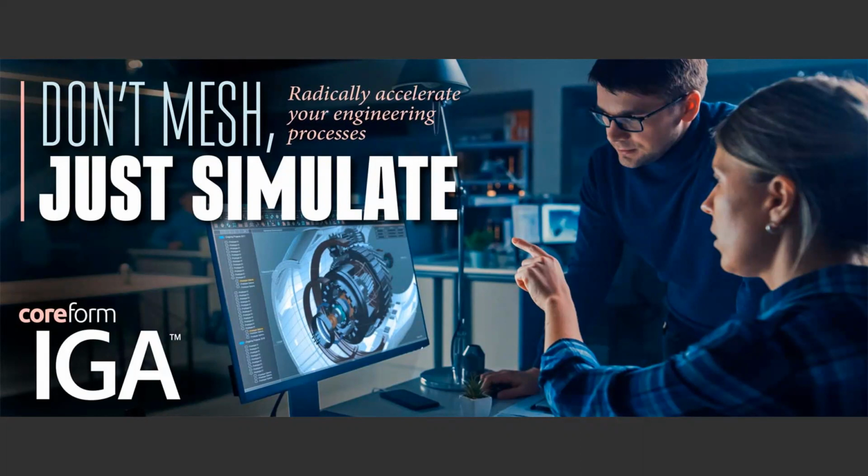In our case, the condition number decreases, or if it increases, it only increases by little bits as opposed to doubling. Those things now allow you to efficiently use iterative solvers as opposed to direct solvers on the linear equations. So all these things are being pieced together, where we're seeing that we can be much more computationally efficient than traditional approaches or traditional FEA.